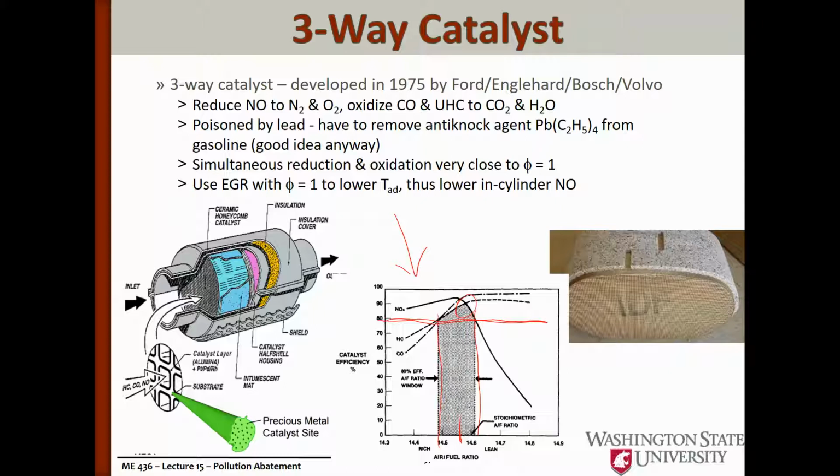Okay, so that works for a gasoline engine, which can always operate at stoichiometric because you're putting in this charge of fuel and air. It's not going to work for your diesel engines. So we'll come back to a different technology that works for the diesel engines.